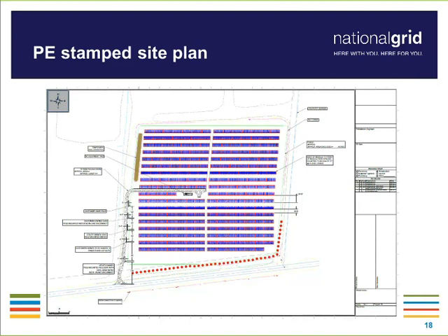understanding there are slight as-builts from time to time, what would be expected at the project. So this example shows a lot of the key components that we would be very much interested in. One of which is obviously the site location. And a key part of that site location, which hopefully carried from the beginning, would be something like a north arrow. Like in this project, there's a north arrow or a compass shown in the upper corner.